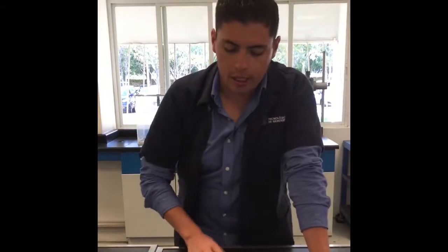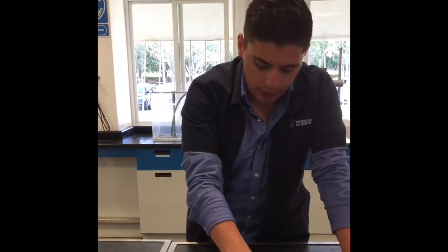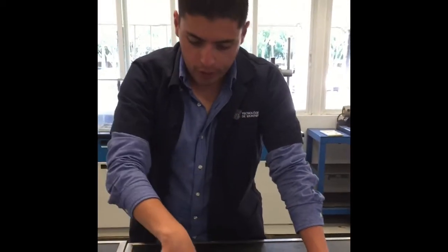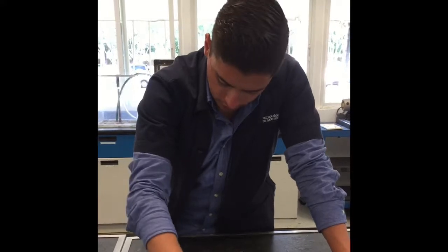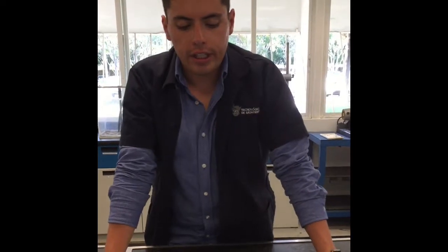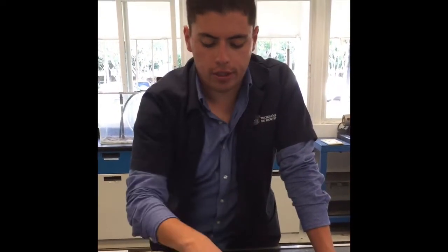And also we can see that at room temperature, they absorb more energy than the ones that were in cold temperature, because for this one it's more, this one 36 and this one 41, and for these ones, the 1018 only absorbs 26 pounds-feet, and the other one, the 1045, absorbs 6 pounds-feet. So we can see that when they have lower temperature, we have a brittle fracture, and we need less energy to have the fracture than the other ones.